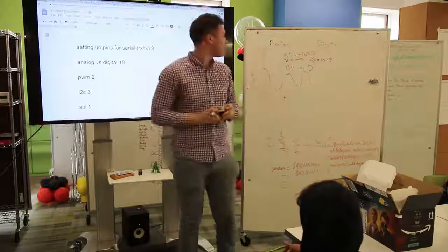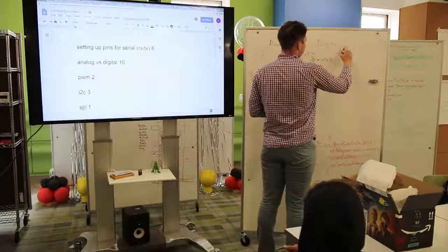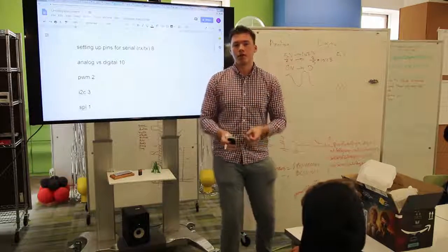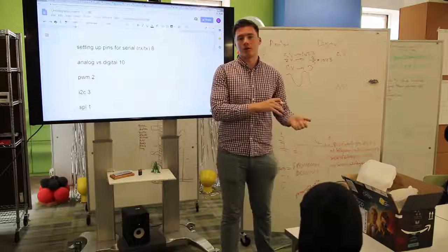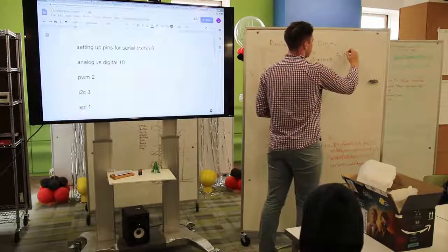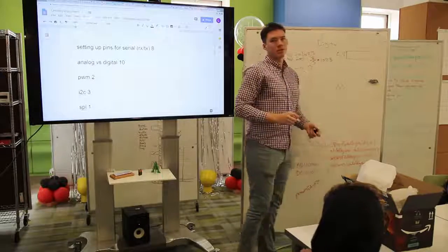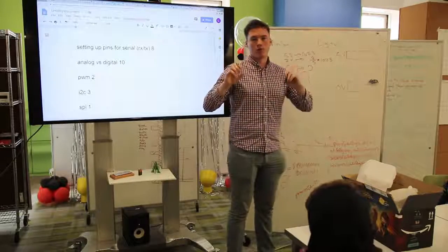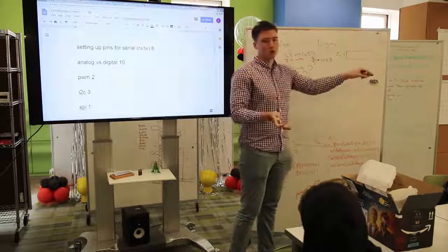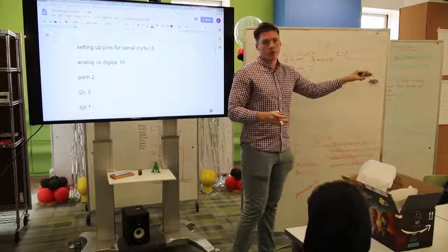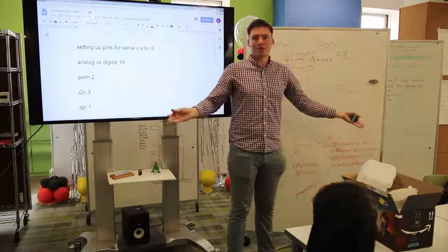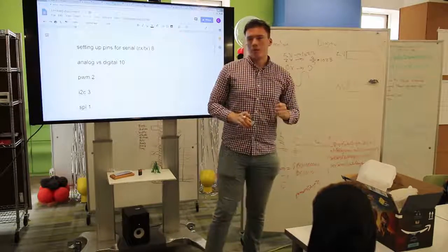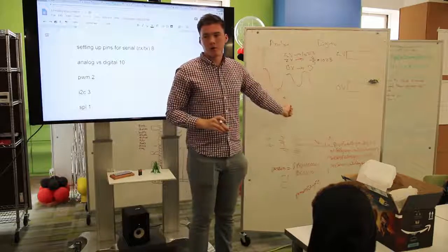Generally speaking, you have the 5 volts and the 0 volts. But when you input to it, you're not going to have exactly 5 volts for high and exactly 0 volts for low. So it says, so long as you're near 5 volts, I'm going to read a high, and so long as you're near 0 volts, I'm going to read a low. That's your margin for noise, your margin for error. Depending on how large the noise margins are tells you whether you'll get a 5 or a 0. You gave a good answer when you didn't answer, because I don't know what to give you if I put in 3 volts either. That's the gist of how analog works with Arduino, how to use it.